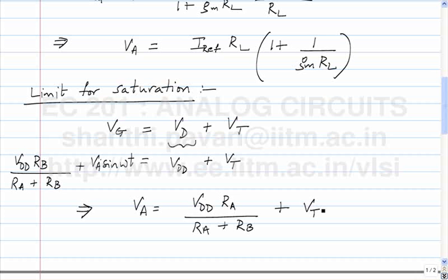Going up. So is this the same thing that happened in the common source amplifier? Think carefully. In the common source amplifier, when the gate moved up, was the transistor going into triode or saturation? Here also it goes into triode.